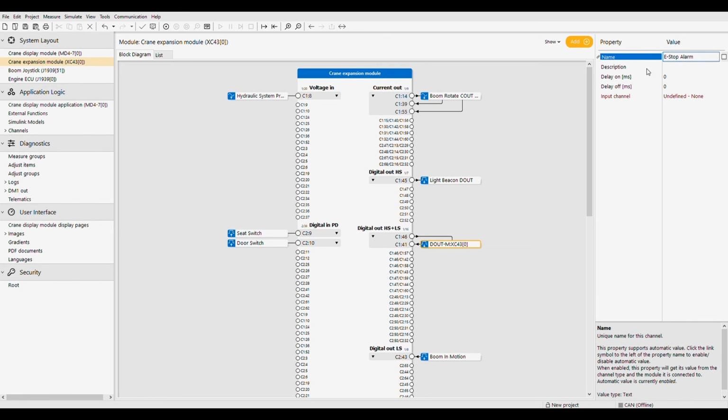Regardless of which outputs you select in your design, always refer to the manual for load requirements, as well as any output controlling a valve or other inductive load that must have a clamping diode for protection. We will cover the PWM and diagnostic outputs in a future episode.